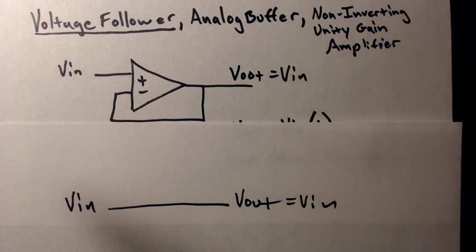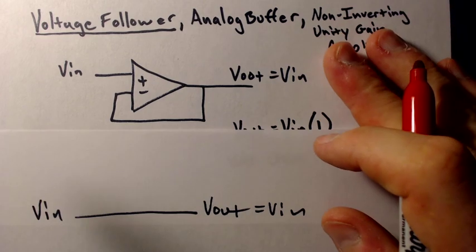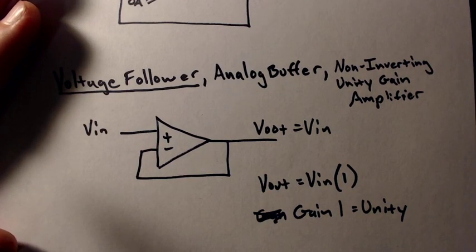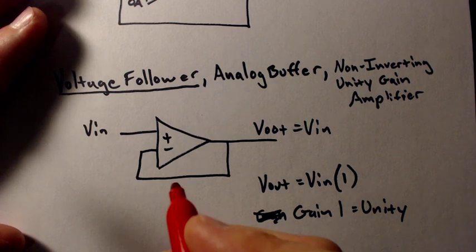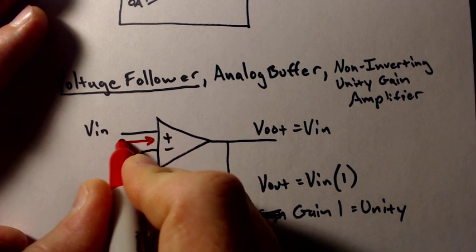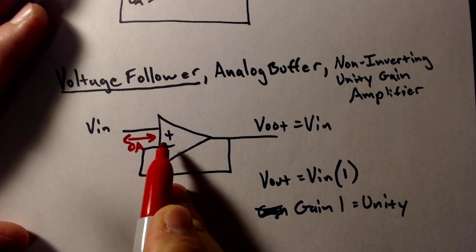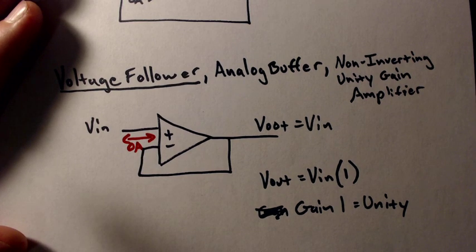Except this op-amp does something really useful for us. And if you go back to that common emitter amplifier circuit and you look at how the impedances mess with us, all of a sudden this is now going to make a lot of sense. Why would we use this circuit? Remember, I said earlier, most useful op-amp circuit in the world. Because 0 amps is flowing in or out of this input. This wire doesn't take any current.